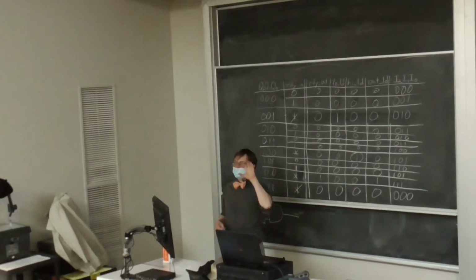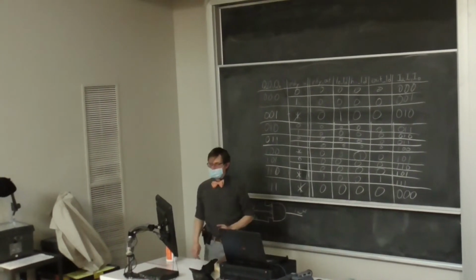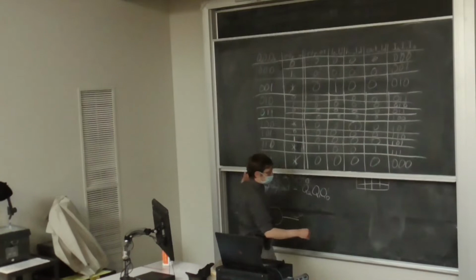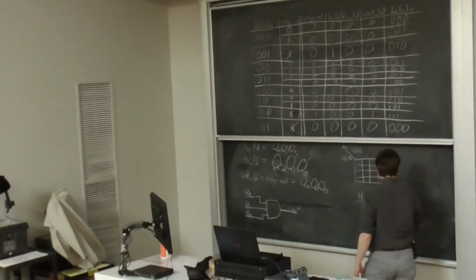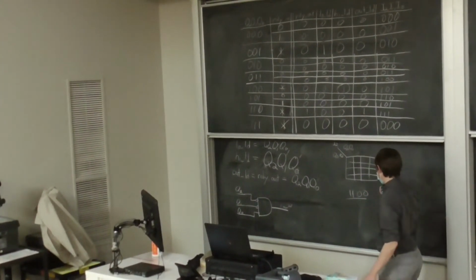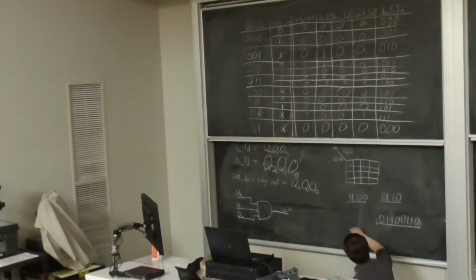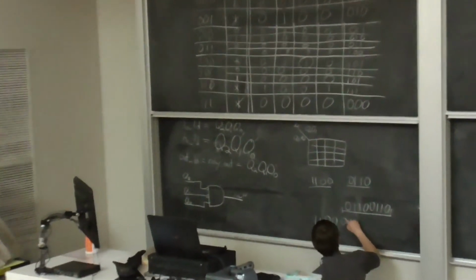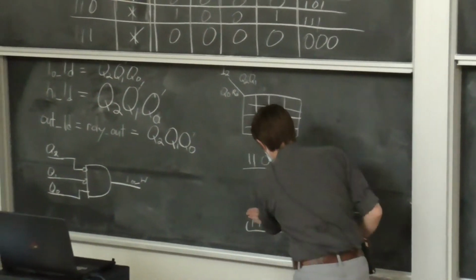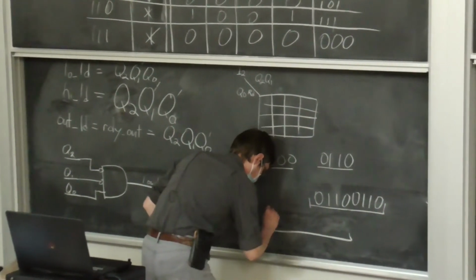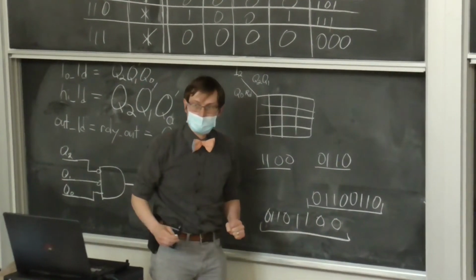If you did it that way, it would be load one, load the other and the first one at the same time, smack them together, and basically you would get, for an input like 1100 as the first bit and 0110 as the second bit, 01100110 as your output instead of the correct answer, which would have been 11000110, which is what you actually wanted. Or this flipped. Yeah, it would be the other way around. But you get what I'm saying, right? Yeah, that's helpful. Thank you. Okay. Thank you for your question.